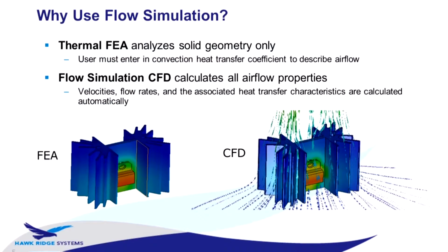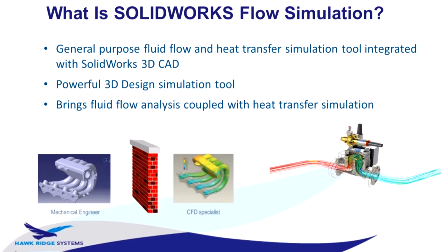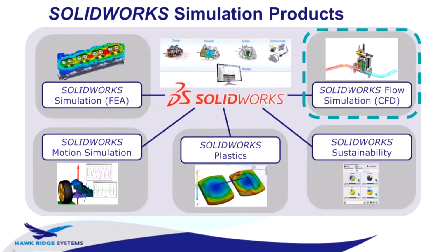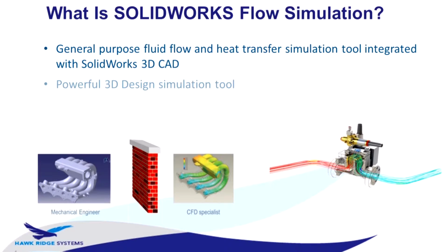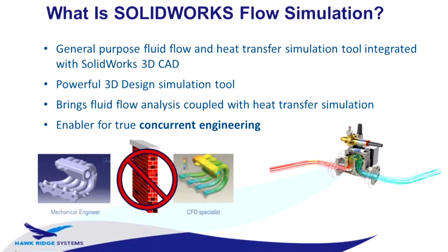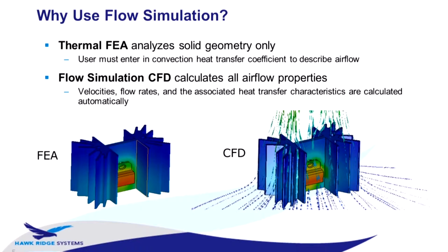Now, some of you may be aware that we also have a thermal study that's part of SOLIDWORKS Simulation Professional. If I go back here, SOLIDWORKS Simulation Professional is just one of our SOLIDWORKS simulation tools, part of the FEA family of products. And so sometimes a question arises: why would you use Flow Simulation for a thermal problem when there's also this thermal study in the SOLIDWORKS simulation tools? And the answer is that the thermal study in SOLIDWORKS Simulation Professional is still what we call an FEA, finite element analysis study, which means that it only analyzes the solid geometry.